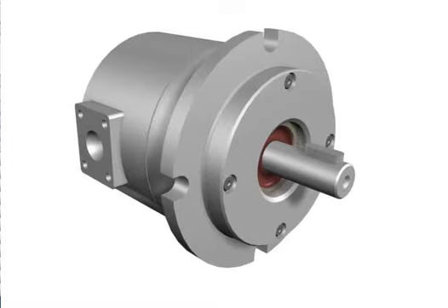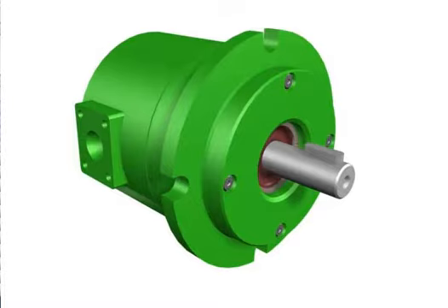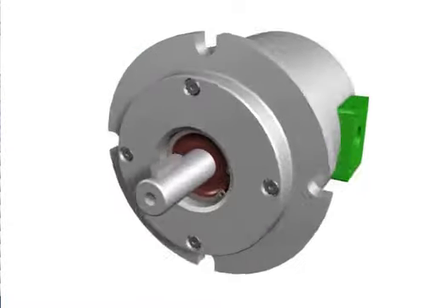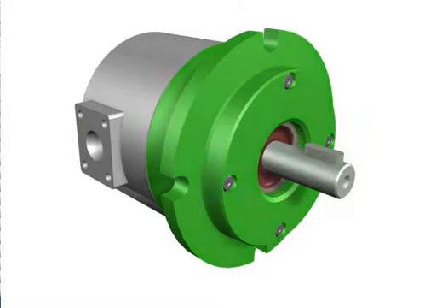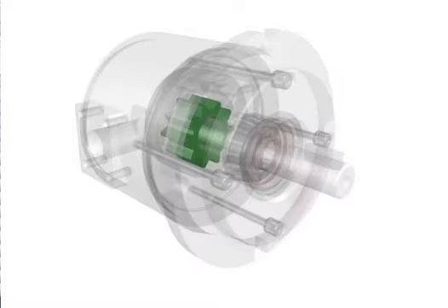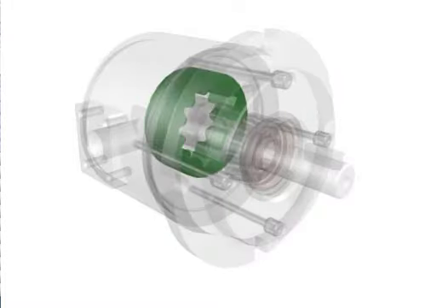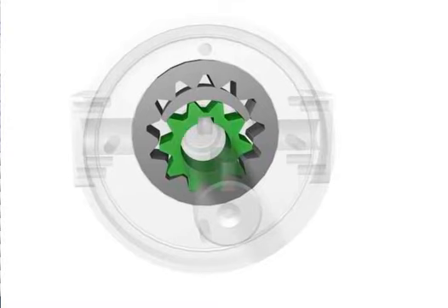design. The main components of the crescent pump include the housing with a crescent seal and ports, the end cover, the input shaft, the drive gear, which is an external gear, and the ring gear, which is an internal gear. The drive gear, which has fewer teeth than the ring gear, sits offset in the ring gear.